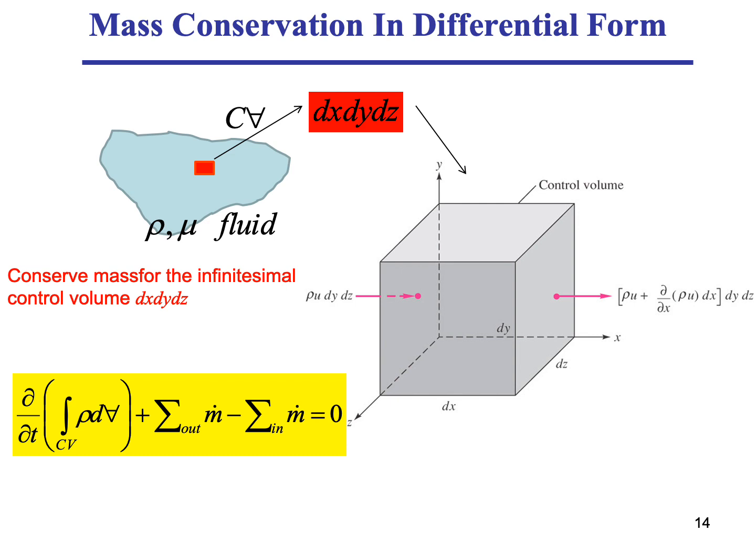Now let's look at a quantity. Let's look at the mass flow rate coming through the face x, because it's perpendicular to the x direction. So this is the face x that we are talking about, and the area of face x is this distance, which we call dz, that's the area of this face, times dy. And the velocity perpendicular to this area is the velocity u.